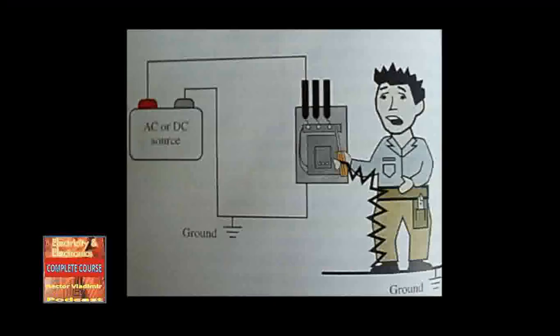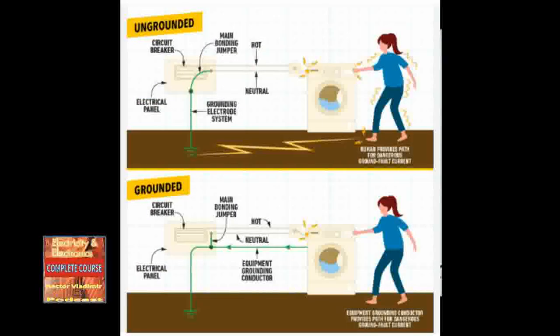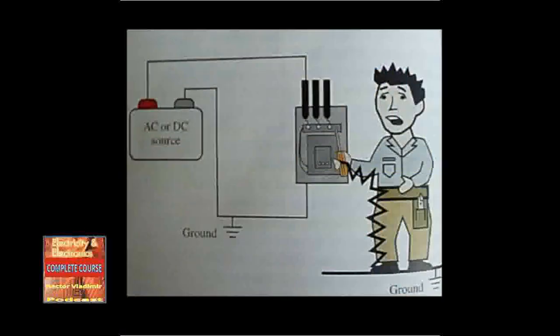Electric shock. Almost all electrical systems contain a ground. A ground provides a safe path for an electrical fault and has a 0-volt potential. It is typically constructed by connecting a conductor between one of the electrical system conductors and the earth. On AC systems, the neutral conductor is grounded. On DC systems, the negative conductor is grounded.